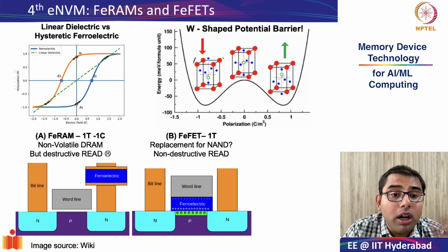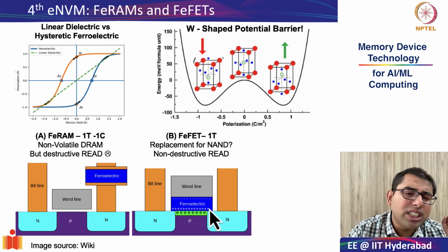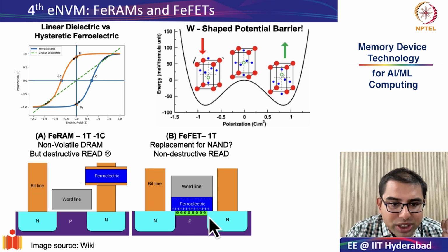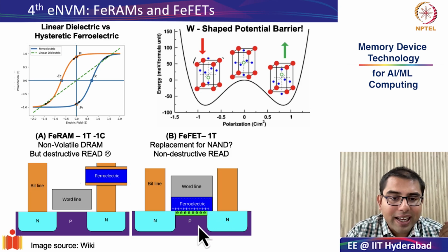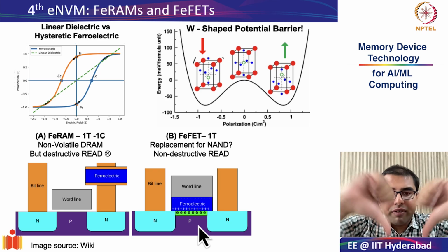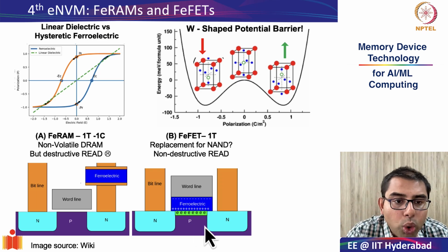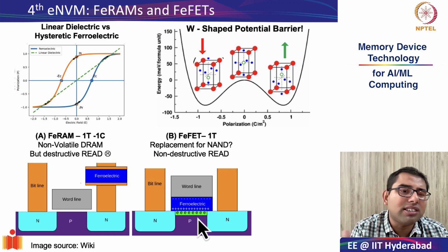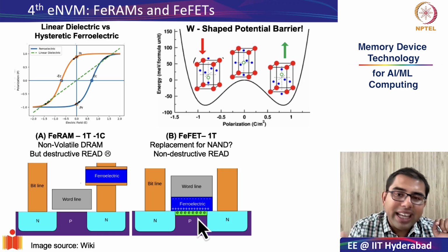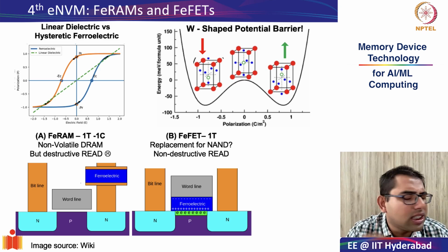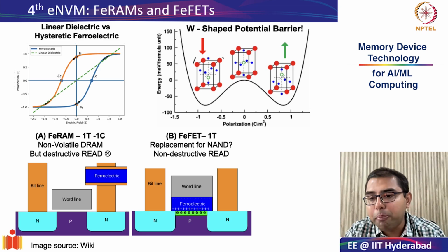So what is the principle of working for the ferroelectric FET? It's very simple. By switching the polarization, you can either induce electrons at this particular layer, which is at the interface of the ferroelectric and the p-type substrate, if you have up polarization. If you have down polarization, you will be able to remove these electrons. And therefore, just like your NAND flash worked by having two different threshold voltage values depending on trapped charges, this is also the same principle.